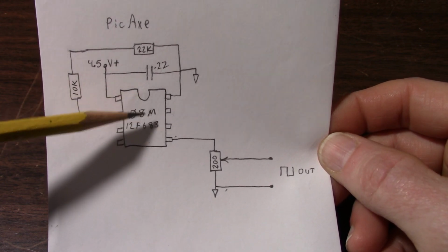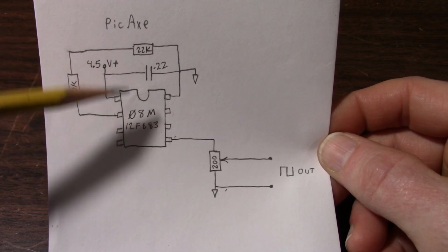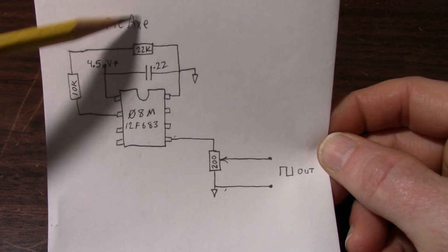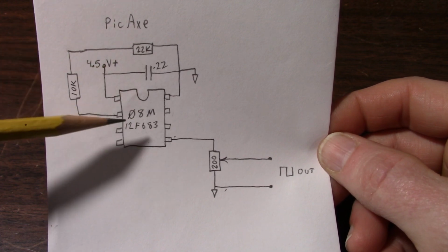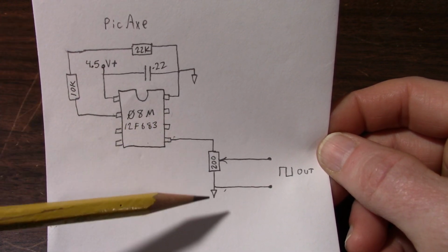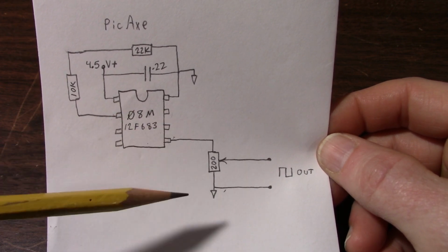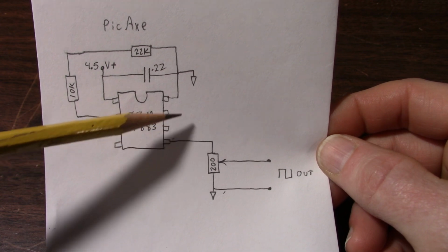Well, I mean, it's all on one chip, but it's separate from the microcontroller in that you can go off and do other functions and wait for input and things like that, and it won't affect the PWM output. It'll keep running at whatever frequency and duty cycle that you set.